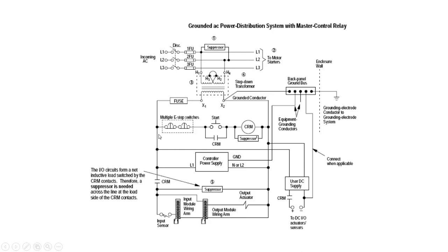Well, it's hardwired, so the CPU is always on, which is good, because every time you hit stop, the CPU would go off, and then you'd have to turn power back on and wait for it to boot up, just like you have to do with a computer. So basically the CPU is always on, we're just turning off the input and output modules.